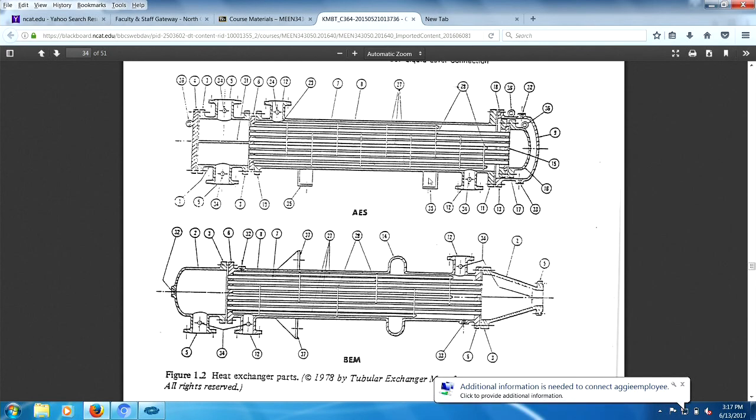The shell would be vertical and you would insert vertically downward. That was perhaps the best. If you insert it horizontally, that'd be a first-class pain in the neck because you got a lot of dragging going on. You can't use any lubricants either. It's not allowed. It's not a good idea. So that's the third hold point.